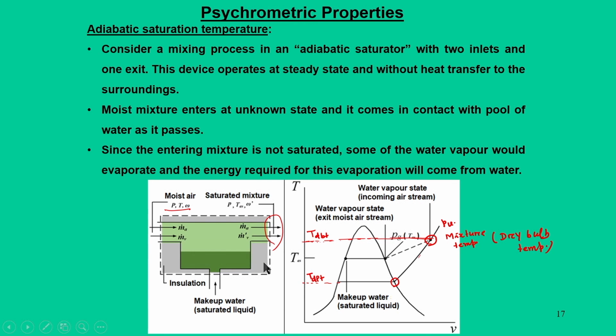Now, when you say a complete adiabatic process, how are you going to locate that state on this temperature-volume curve? In this particular way we define it, and we go along a dotted line, and this dotted line represents that it is an adiabatic process. When you keep adding moisture into this air, we reach another point, that means we reach this point.